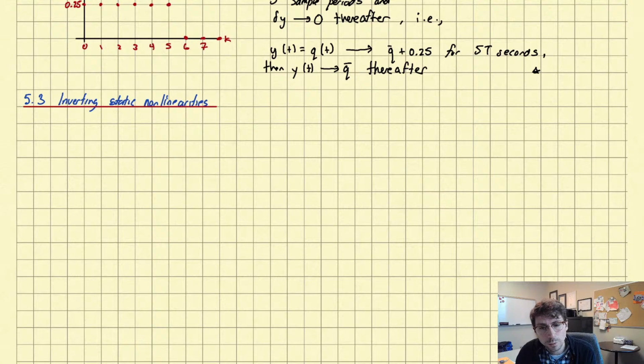Right? So let's just think about the high-level idea here. So far, the strategy for dealing with nonlinear systems is to approximate them with a linear model. The concept in this section is a little bit different. It's not trying to approximate them using a linear model, but rather making clever choices of control, let's call them algorithms for lack of a better term, so that the system appears linear. So it's kind of a clever choice of control as opposed to a modeling approximation, which is what we've done before.